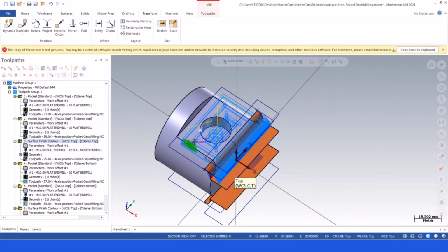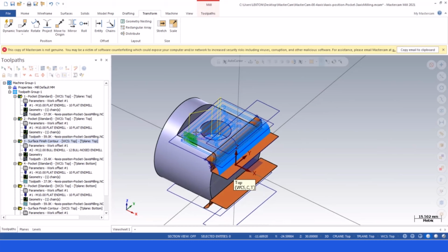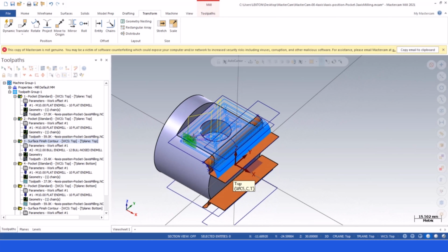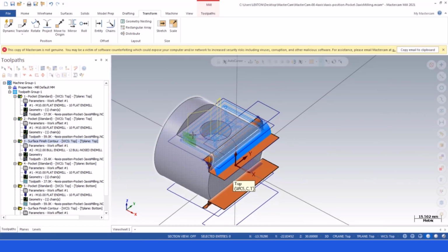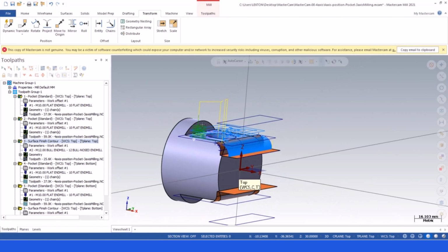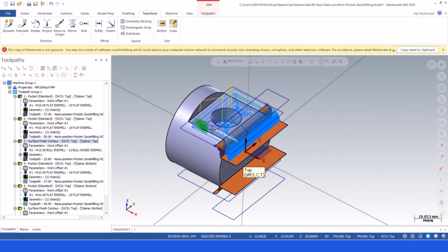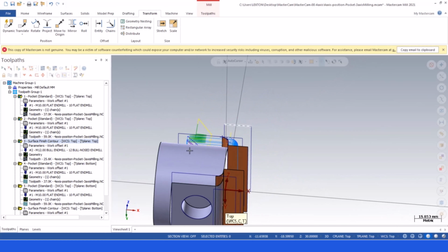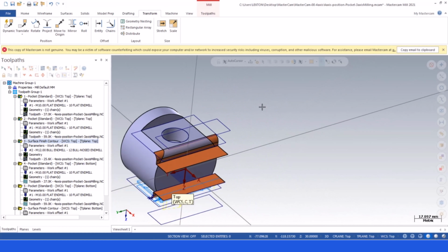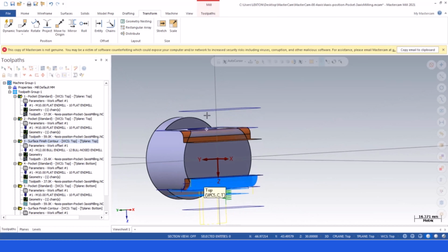Okay, I can create my toolpath, and then I can change my coordinate system, and in my CNC I just need to write A108 and work offset 0, and then I can resend my code again, and we're gonna see the same solution.